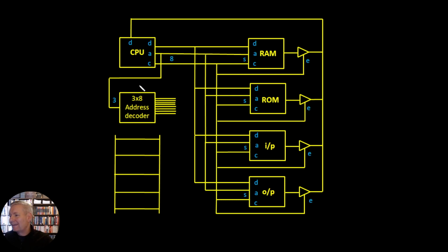So the method that we've used here for splitting up the memory is going to split it into equal parcels of 32 bytes. So that's 32 bytes, that's 32 bytes, so is that and so is that, and we've got a potential of another 4 devices here that we can talk to that are going to be 32 bytes addressable.